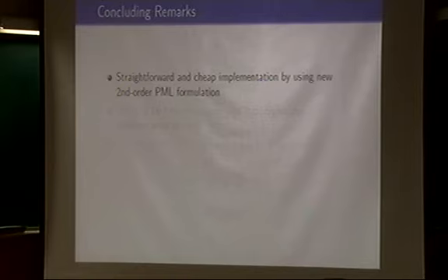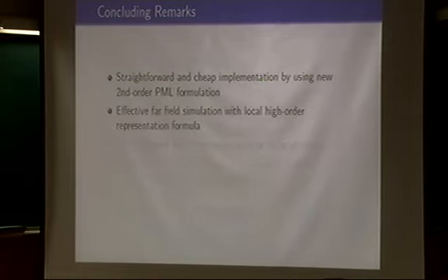So, concluding remarks. Our calculation is based on a straightforward and cheap implementation of the second order PML formulation in the wave equation, Maxwell, or elastodynamic equations. Also, we have effective far-field simulation with a locally high-order representation formula without an integral equation. The third point is that it is easily coupled with finite differences and finite elements.